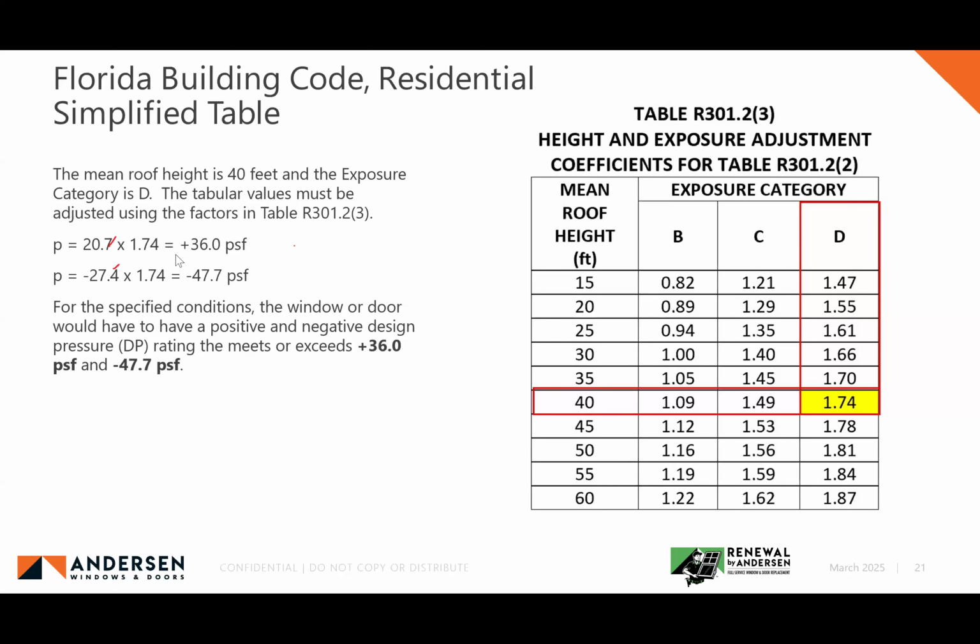The reason for that is because we had to interpolate the effective wind area. Now, when I say slightly, I mean it might be 0.4 or 0.5 PSF. I mean it's that little of a difference at that level. But we're using linear interpolation to get the value between the effective wind areas listed, and it's actually a log graph that the external pressure coefficients are on. So it's not linear, but it will be conservative, just ever so slightly.